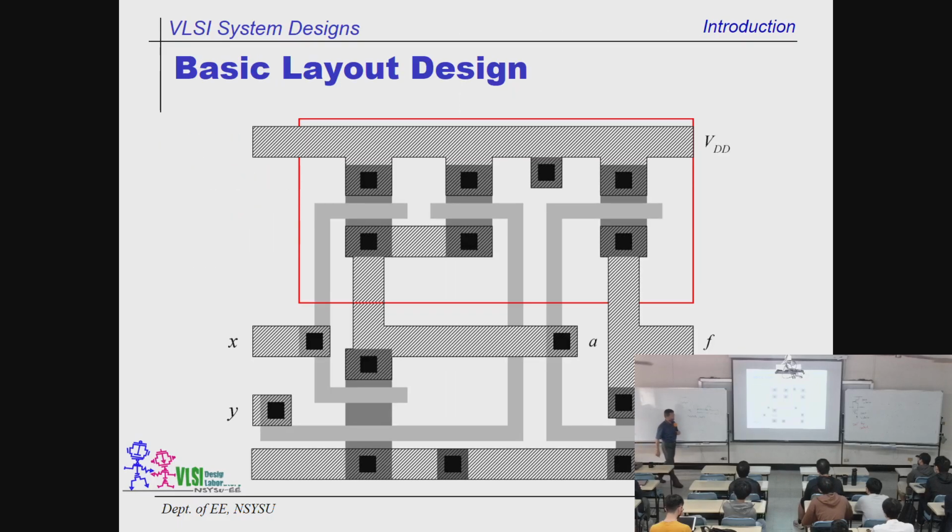See that? This is coupled to the ground. What is this for? This is the purpose of the well contact. It's nothing to do with the logic. You can consider these two extra well taps as janitors. They work as cleaners to clean up all the unwanted carriers.